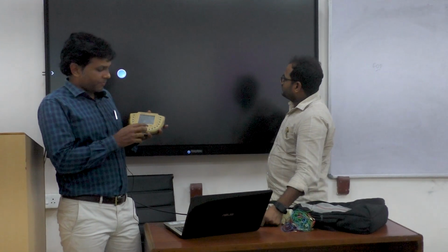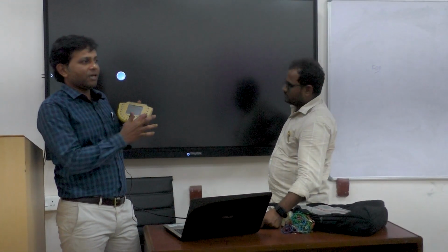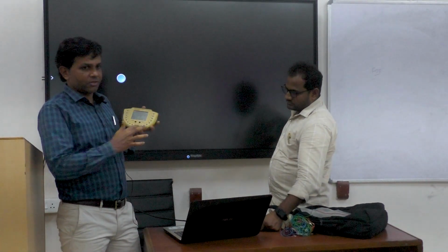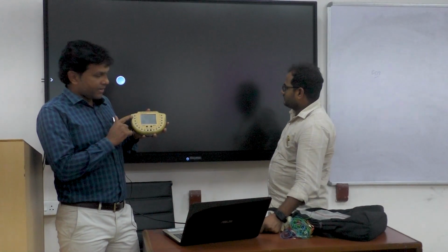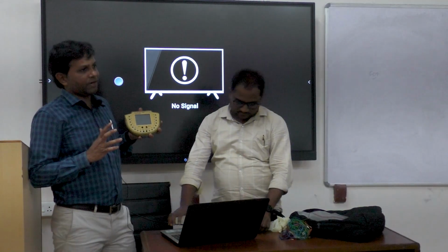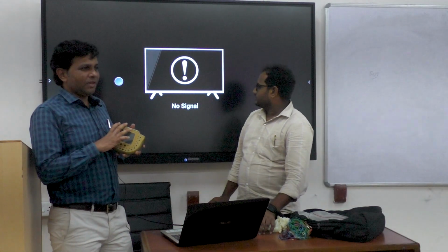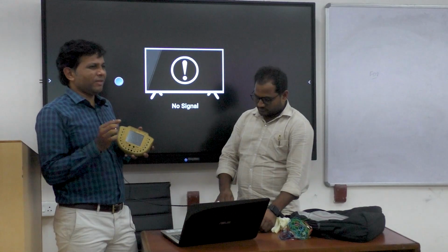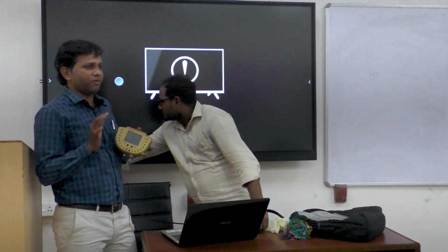So 1 to 8, 9 to 16. There are 16 channels in the data acquisition system. So I can record at a time from 1 to 8 plus 9 to 16, a total of 16 channels I can record the data from. Typically for these small applications we have spoken about, around 16 is sufficient.